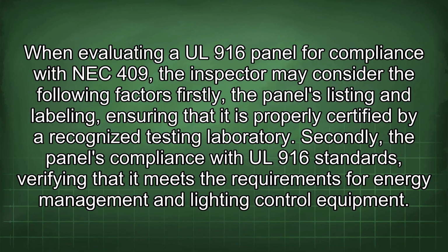Firstly, the panel's listing and labeling, ensuring that it is properly certified by a recognized testing laboratory. Secondly, the panel's compliance with UL 916 standards, verifying that it meets the requirements for energy management and lighting control equipment.